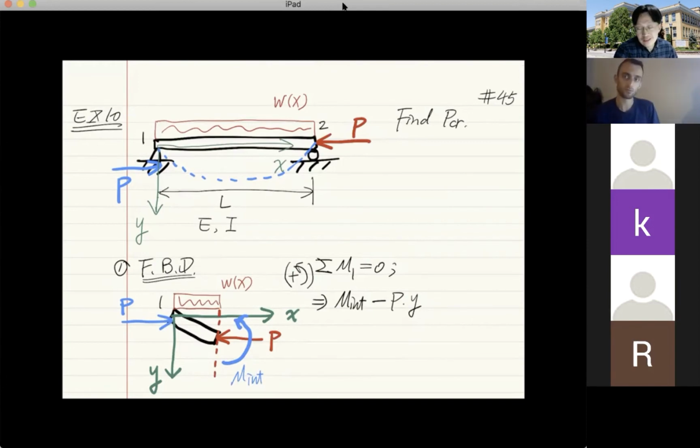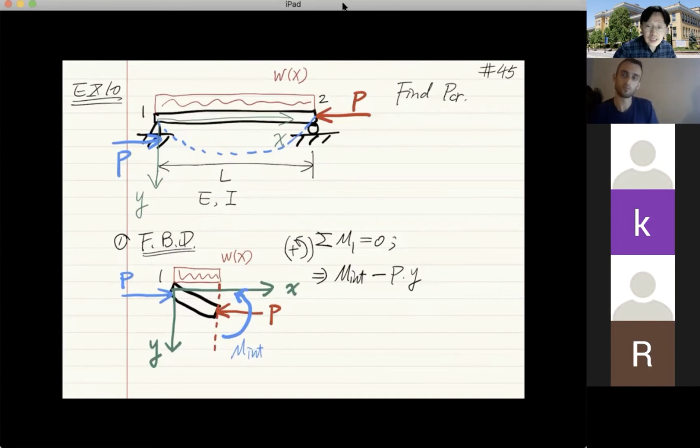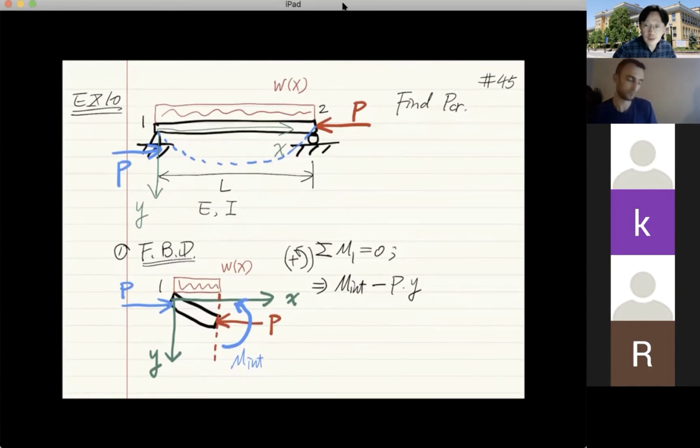Even though that value is very straightforward, we forgot to formulate it. So next time, please be careful before you start formulating your moment equilibrium expression. Make sure you consider all kinds of forces. This kind of mistake is definitely not a good practice. We forgot to consider the vertical reactions at support 1 and support 2.